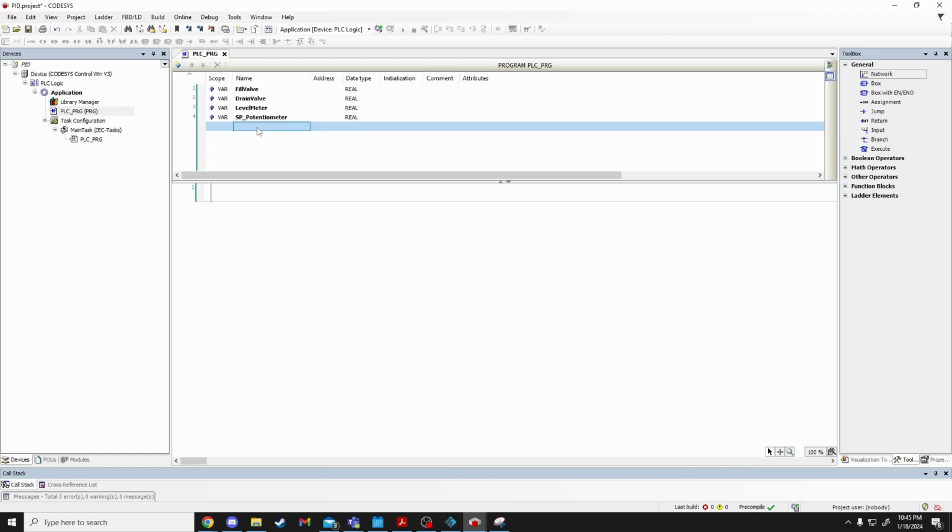We can give it some load, some coil, which in our case is going to be the fill and the drain valves, and we are going to use those to correct that value. So it's going to listen for the current state, compare it against the desired state, and then apply a correction via our loads. We need a couple variables for this.